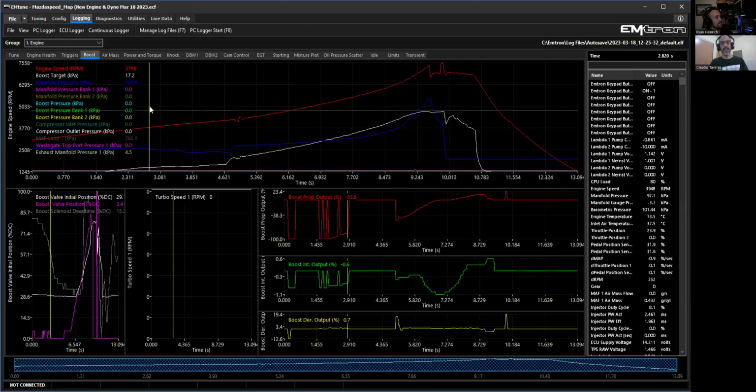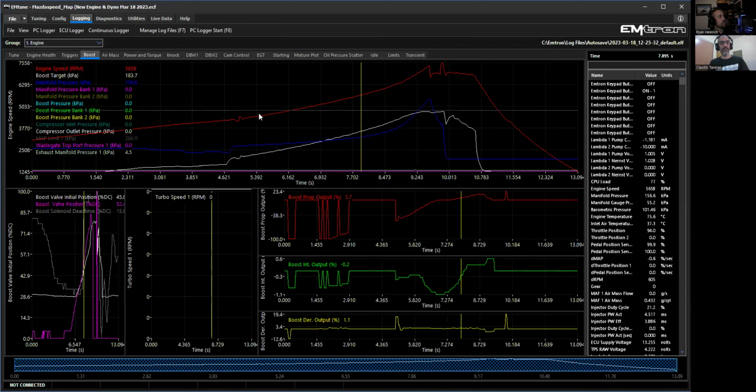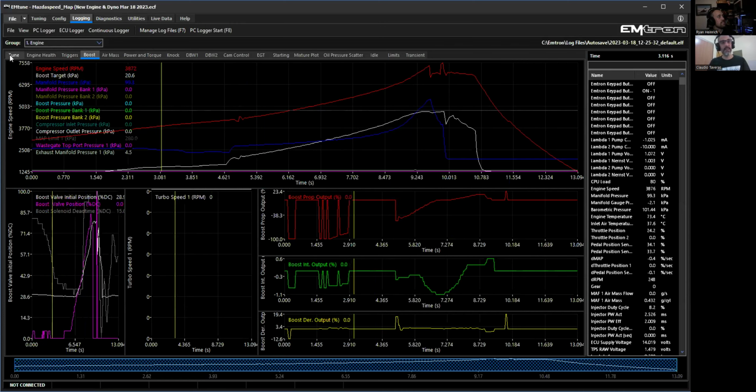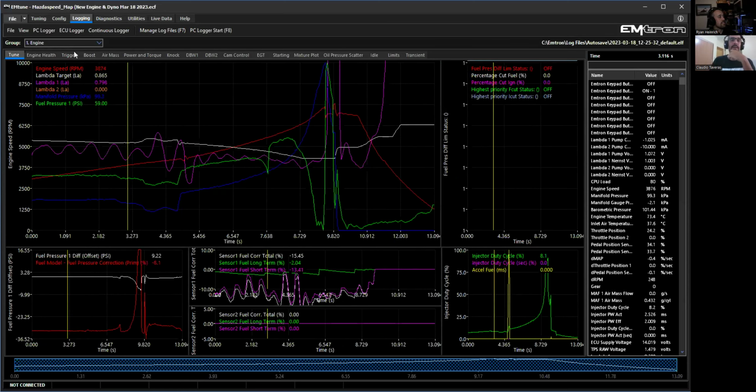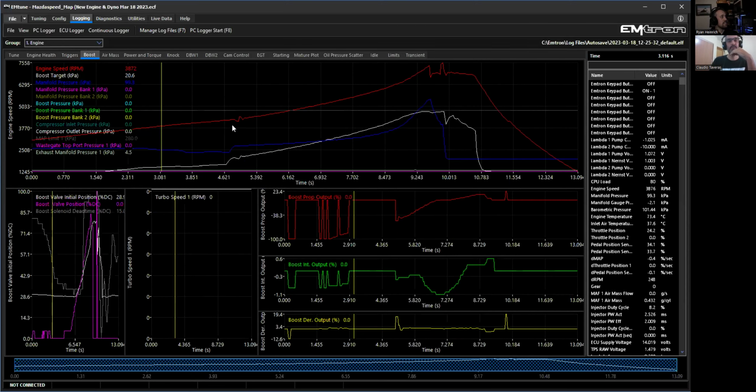In this particular scenario, we don't have a lot of stuff on this particular card that would have made this more useful. That's why I kind of stuck to the tune one, which is basically just what I need. But you can put stuff on here to your heart's content and analyze this till you're blue in the face. Of course, every system will have a more advanced or simpler data logging scenario. It's up to you to make use of it. Don't think of it as too simplified. Try to put it to work and log your RPMs, your pressures, your sensors, and everything. Then you should be able to at least make heads or tails of what's going on and how to improve it.